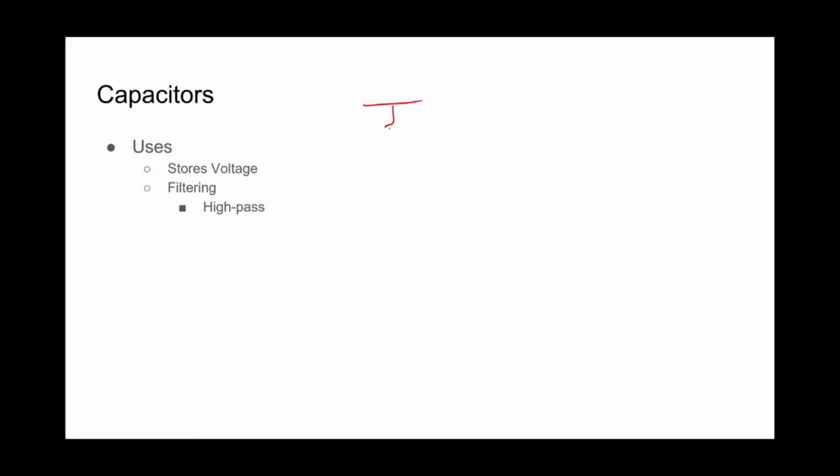Hopefully you remember when we talked about voltage dividers, where we have R2, R1, V in, and V out. As a quick refresher, V out equals R2 over R1 plus R2 times V in. Now this is great for voltages, right? Because if you remember, as current passes through here and not through there, it causes that voltage to drop, giving us this nice, neat little voltage divider.